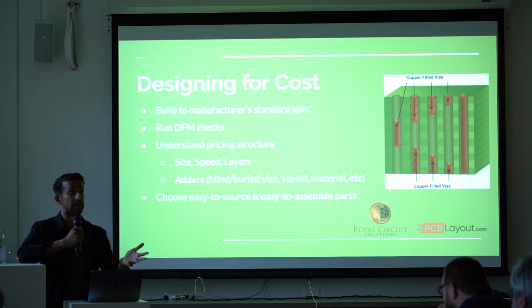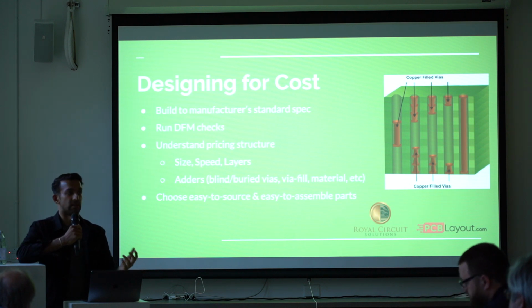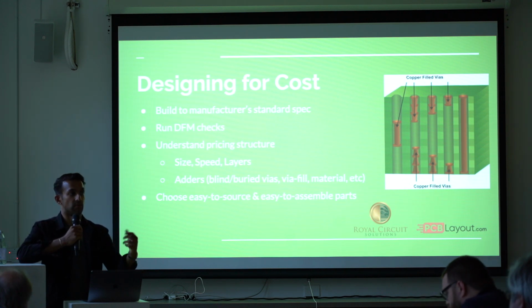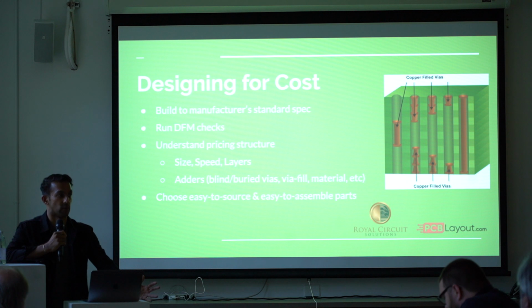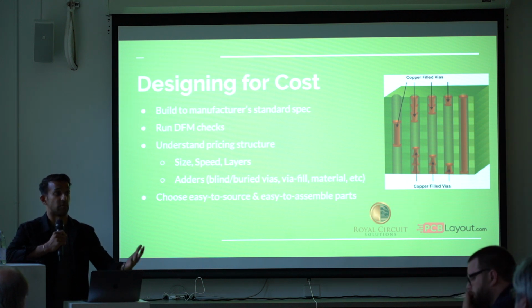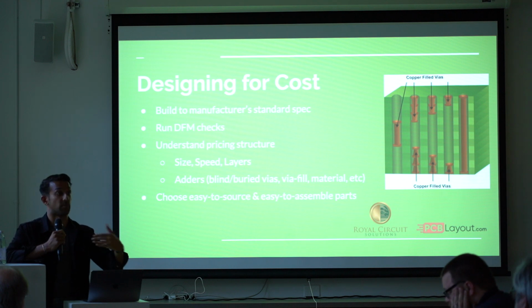for fab, because all we're doing different is we're imaging it. But there's no difference besides maybe the time it takes to test, which we don't charge for anyways, and the time it might take to do any sort of rework, like with final QA or an AOI, the optical inspection. But for the most part, we run an entire 18x24 or 21x24 panel through the shop, no matter what. That's the only size we can run through all our machines and plating processes and presses.